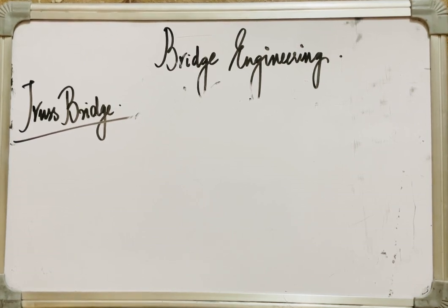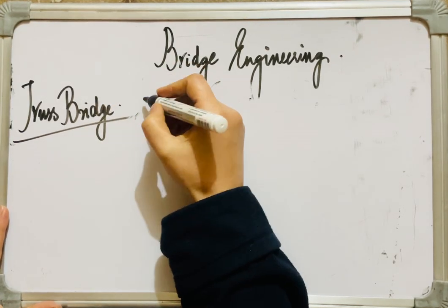So in this truss bridge, the bridge deck is supported by means of steel trusses, which are interconnected triangular sections. They provide exceptional strength and are capable of handling both compressive loads as well as tensile loads, that is, dynamic loads, and they are renowned for their sturdy framework and can be found worldwide. And a truss bridge of a simple span essentially behaves like a beam and carries vertical loads by bending or flexure. Now let's study their advantages.